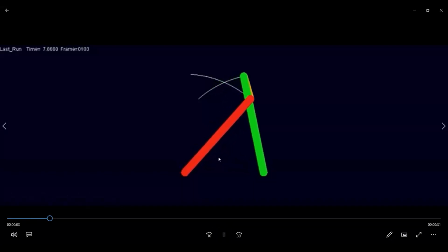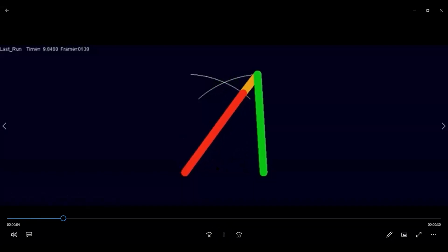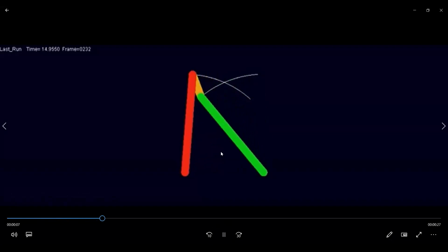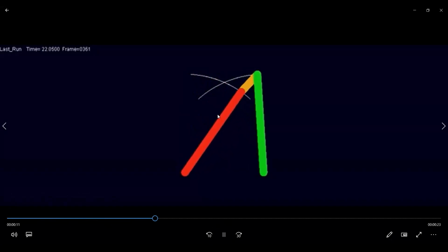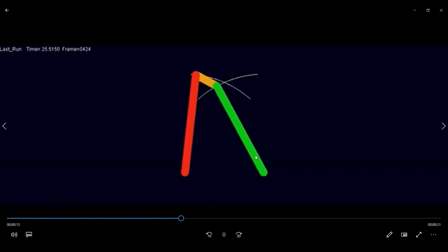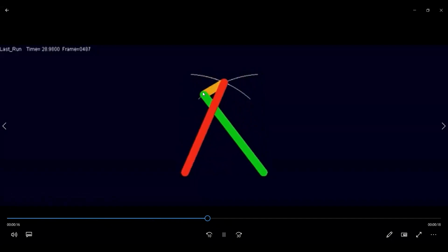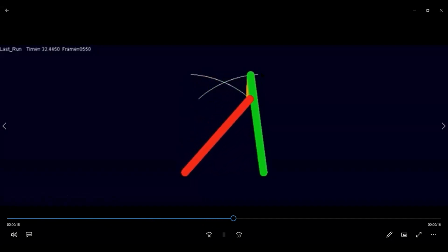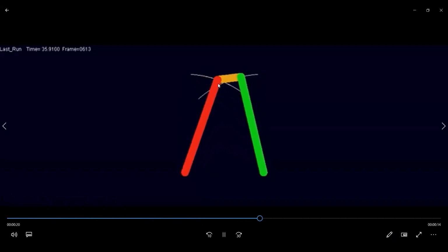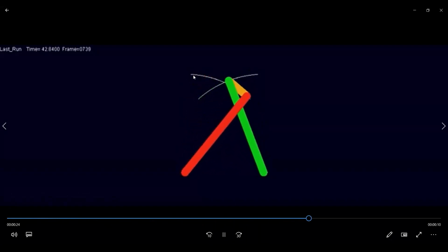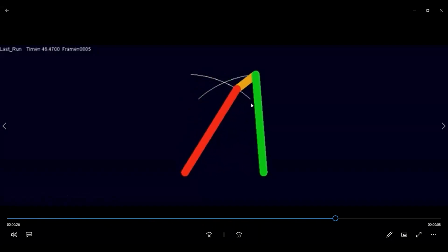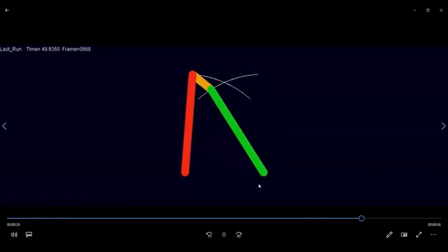Okay. So it is a double rocker mechanism, you see. Both of these links, this red and green, are just oscillating in their path. From here to here, and the red one is on this arc. Its path is on this arc, so complete rotation is not possible.